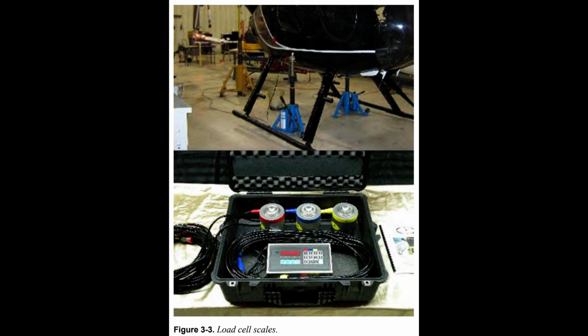All scales for aviation use, manual or electronic, must be protected when stored or shipped, and they must be checked periodically for accuracy. The maximum recognized period between calibration checks is 12 months, however, this period may be reduced by an airworthiness authority dependent on the conditions of use. Scales in daily use may require a shorter interval and/or testing to determine the continued accuracy of the unit. Scales should be returned to the manufacturer for proper calibration and testing.